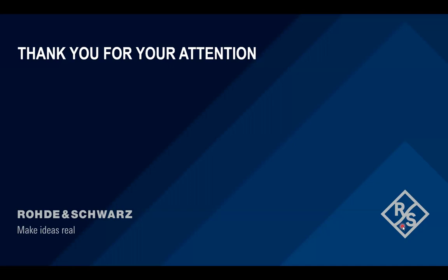If you remove that one later on, you might have a change in the parasitics of your PCB, and this might cause a different behavior. So typically, we have the recommendation right now to have two designs. The first one is specifically for test purposes, where you will have these dedicated test points in, and the second one will later be used for the production, where you do a last verification with some soldering made, where you'll have the connectors added by a small wire there.